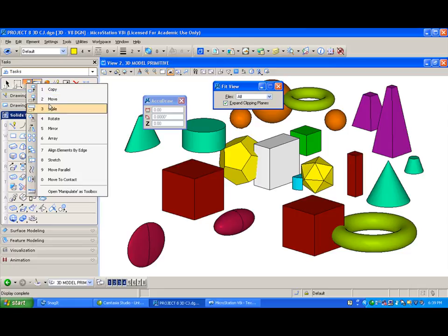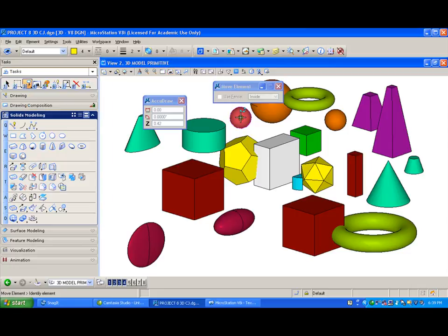And again, you can take these primitives. If I want to take the center of this sphere and place it, spacebar C, on the center point of this box, you can just do it like that. If I want to take the same sphere here and place it on the center of this cylinder, it's automatically got a snap point there. Or you can place it out here on the center, hit the middle mouse button and hit O, and just pull it in, hit enter. Remember, enter works just like it does on any two-dimensional drawing. You can still lock the axis in whichever direction you're going and place your solids here.